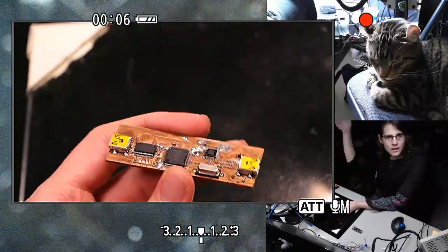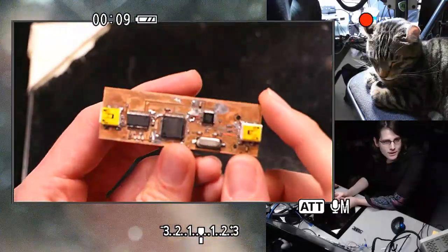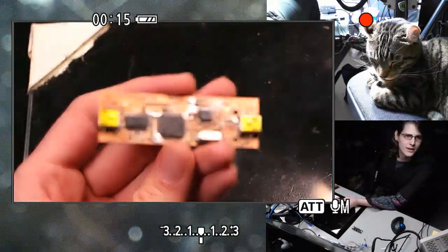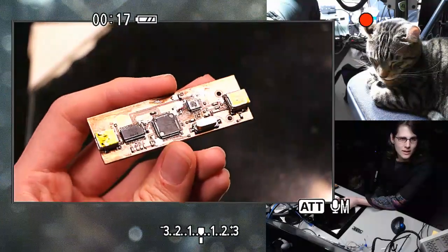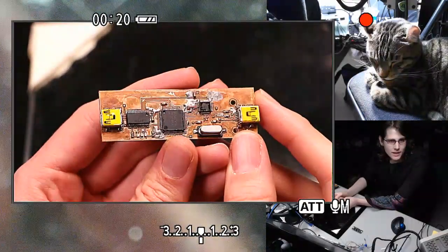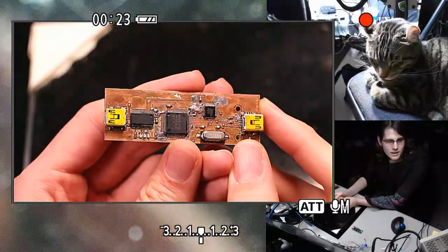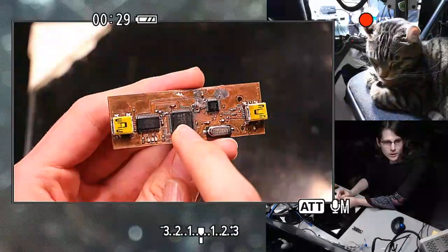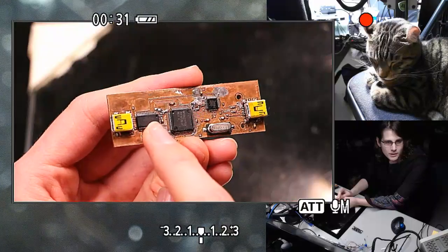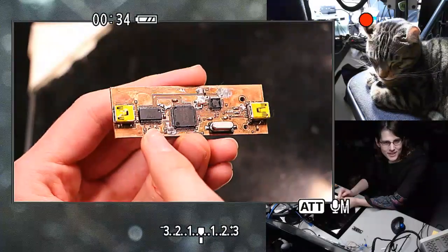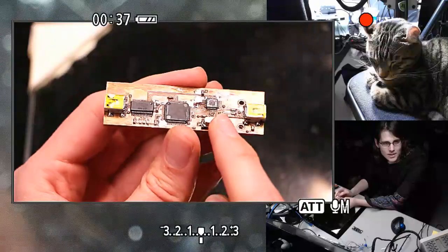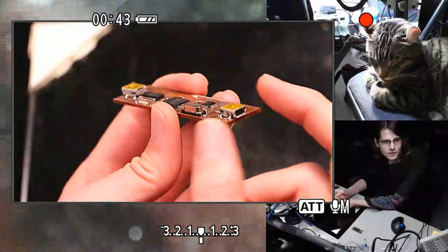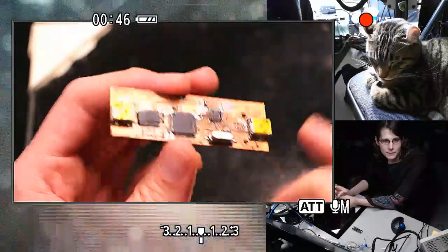So, I think I've got plenty of footage of this for the video already, but just for some additional context, this is the Facedancer board that we'll be working with. It's a thing that simulates USB devices. That's an MSP430 microcontroller, and this is a USB serial adapter, an FTDI chip, and then this is the SPI attached USB host or device controller from Maxim. And that's the thing that this is all remote controlling from Python.